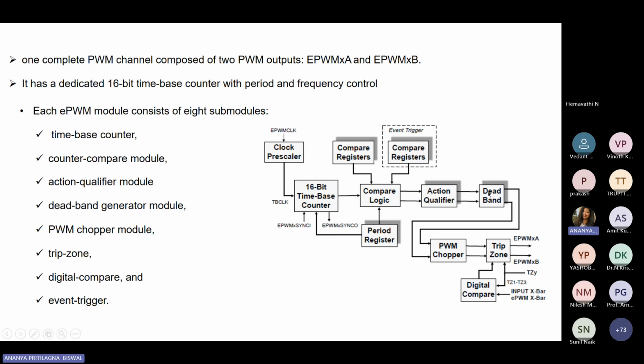And the deadband is, I can say, the main advantage of this controller. For inverter operation, while we are operating a single leg of a single-phase split inverter, in a single leg there are two switches. From the time one switch turns off until the other switch turns on, there should be a time gap. Otherwise, a dead short circuit may happen. So we use this deadband unit.